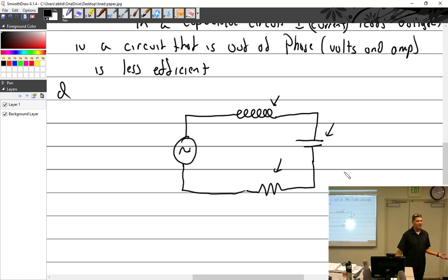By the time the capacitor fills up and they realize that the capacitor is a dead end and they should have gone through the points, they all turn around and run back, but the points are already too far. They can't make the jump. So it keeps the points from burning and arcing. We'll cover that again in 2 weeks. But for now, the capacitor balances out the inductors. Or if you had a bunch of capacitors, don't know why you would, then the inductors would balance those out.